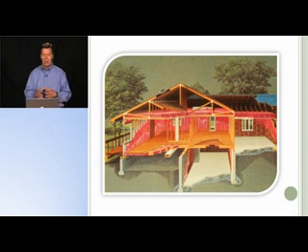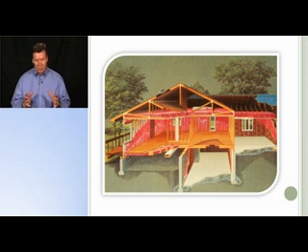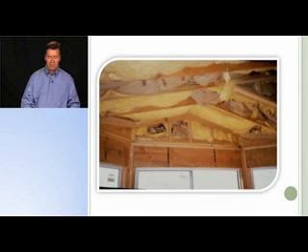So for example here, when we look at our thermal envelope, we're seeing that our walls are insulated with this fiberglass insulation, the pink areas. We see that our floors are separated from the crawl space by floor insulation. Sometimes they insulate the perimeter of the foundation walls as well, or instead of the floor. And then we also have the insulation at our attic levels. But when we talk about a thermal envelope, this is a pretty good visual that describes that.